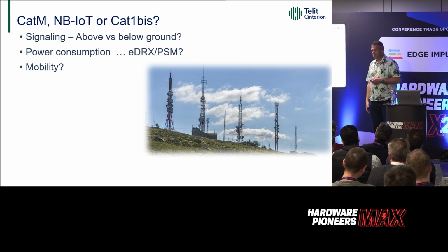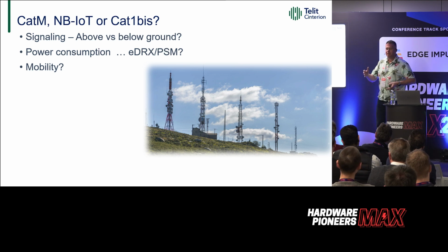Mobility, as I just mentioned, is useless for narrowband IoT. I know there are people out there saying, oh, you can do a cell reselection, but it's a faff. Just don't bother trying. You're better off using Cat-1bis.